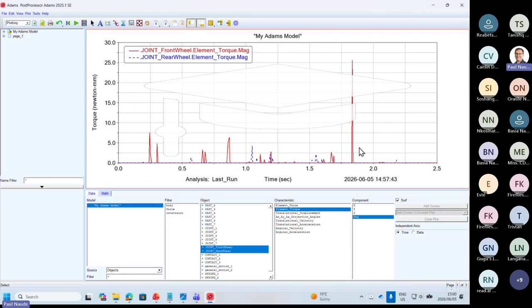Don't think that because there's one single spike at a specific value that you now need a motor that can supply that amount of torque all the way. That is definitely going to give you a big surprise, because in reality we just need to give it a little bit of torque, bits and bits of torque, to get that exact motion.